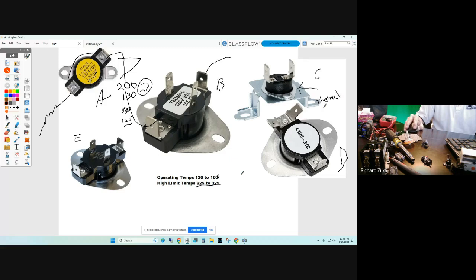Sorry, I should have typed it, but thermal cutoff. And the thing about these is that those are usually not resettable. Like these thermostats here have that little disc I told you about, like a contact lens, that cycles the switches on and off. This one, usually when it fails, it's a one and done thing. It does not reset and has to be replaced. But that comes with this one.